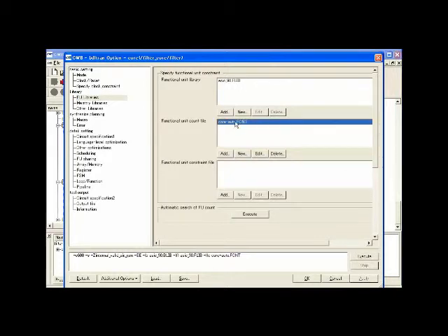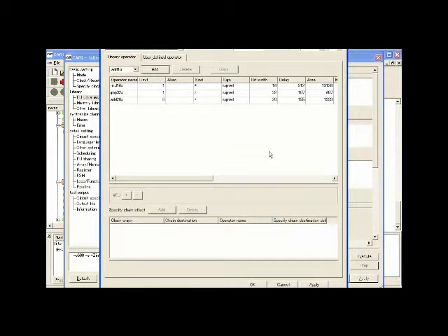and CyberWorkBench automatically generated the constraint file where we specify how many functional units we allow the synthesizer to use. We can also edit the constraint file and manually overwrite the default constraint file. In this case, the synthesizer would use 1 16-bit signed multiplier and 8 28-bit signed adders. We can decrease the number of adders that we allow the synthesizer to use, and we can easily increase the number of multipliers that we allow the synthesizer to use.